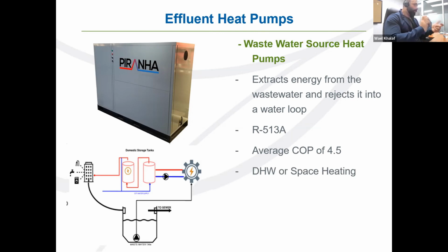So it really depends on the type of building we have. But you're right, generally there's not enough wastewater to heat up a whole building for space heating, though not for domestic hot water production, unless you have a significant amount of effluent or you're able to use very large storage tanks.